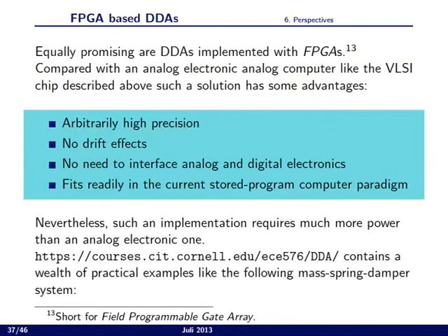If your analog computer is implemented in an FPGA, there is no complex interface. You don't have the need for a digital-analog and analog-digital converter, nothing. And it fits readily in our current stored program computer paradigm.